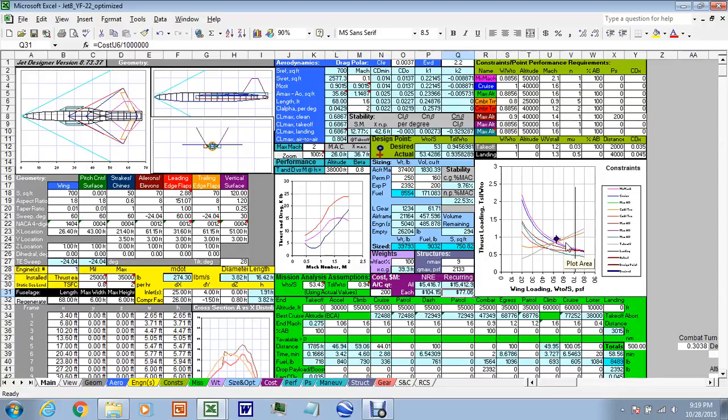Well, the F-119 is the same size as that engine, same diameter and shorter, and weighs less, and it produces 25,000 pounds of thrust in mil. The F-106 could go Mach 2.3 with that thrust, so we're betting that this airplane, which looks and has drag similar to an F-106 and weight similar to an F-106, could do the same thing on an F-119 in mil.